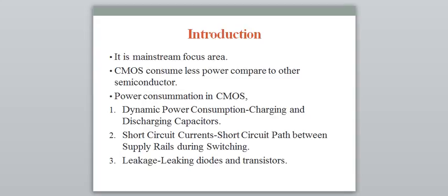The third is leakage. Leakage consumes more power because of the leakage current. The leakage current flows through the thinner gate dielectrics because of current tunneling through the extremely thin gate dielectric. The leakage power is a significant portion of the total power consumed by the designs.